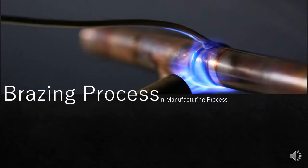Brazing process. So basically the process of brazing has been known for at least 5,000 years and must be one of the oldest of all known metal joining techniques. So brazing is a joining process wherein metals are bonded together using a filler material with a melting or liquidus temperature that is greater than 450 degrees Celsius, or we can convert to Fahrenheit, which is 840 degrees Fahrenheit, but lower than the melting temperature of the base metal.